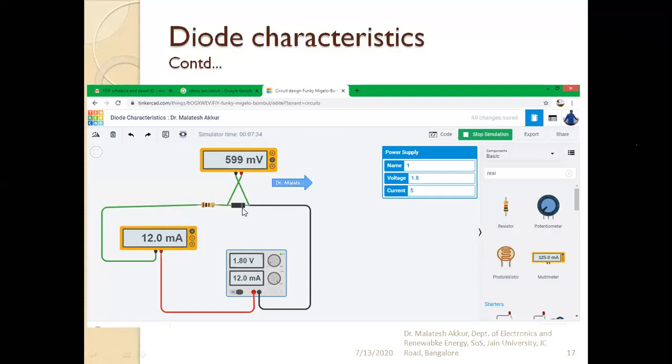That is when the diode is forward biased, when the P type is positive and the N type is negative. Only during that time does the current flow. So this is the main property of the diode, which makes it useful in the rectifier.